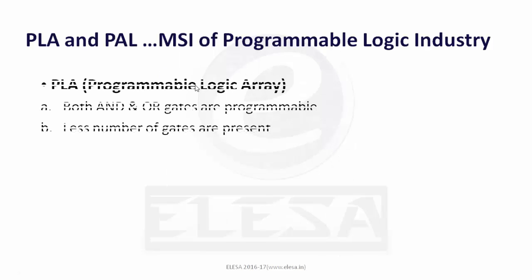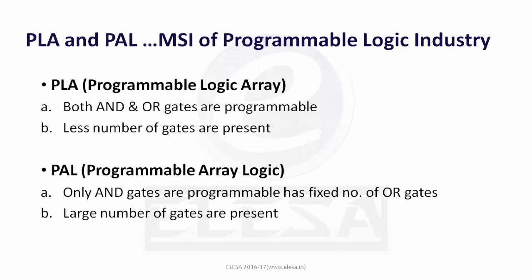Along with the PLA, there is one more technology, PAL, which stands for Programmable Array Logic. The key difference between them is that PLA has both AND and OR gates programmable, as we have seen right now, and it uses fewer gates. PAL has programmable AND gates but a fixed number of OR gates.